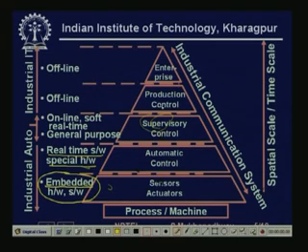For example, one of the main purposes of this supervisory control layer is to update the man machine interface, that is, whoever is the operator has to be shown how the process is performing, plot the graphs, plot various statistics, etc. So these are typically soft real time operations, in the sense that obviously you cannot display a variable 30 minutes after you have got it. But as long as you display it in time, whether you are displaying it within 2 seconds or within 10 seconds is not of much consequence. So to that extent it is called soft real time.